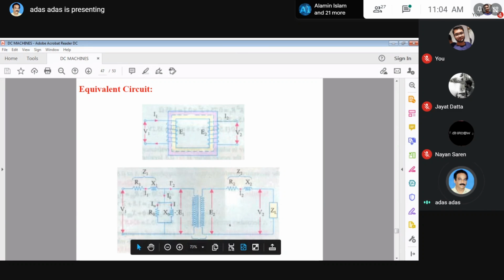X0 and R2. What is X0? X0 equals E1 by I mu. E1 is this voltage, the back EMF or induced voltage, E1 by I mu. Similarly, R0 equals E1 by I omega.